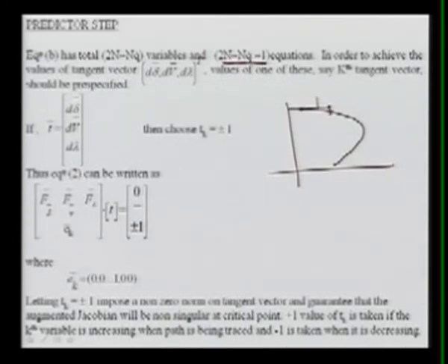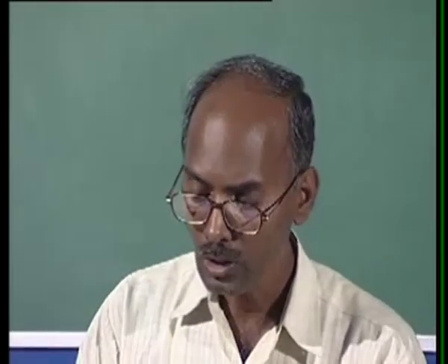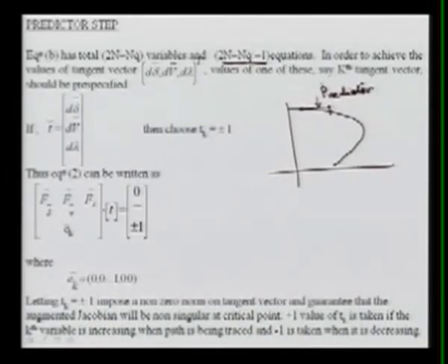So, this step is called the predictor step. Since we have predicted this, we calculate this value with the increase in the load, and then, keeping the load constant, we calculate the actual solution using any conventional load flow algorithm, and normally we use the Newton-Raphson method.